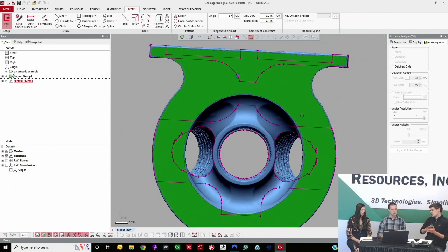So you're using this mesh sketch tool to aid in your alignment process before you even start modeling. Yep. You could consider this part of the modeling process, I suppose, but really this is just preliminary to the modeling process. I'm defining a coordinate system on the scan that I can use to move the scan to the world coordinate system.